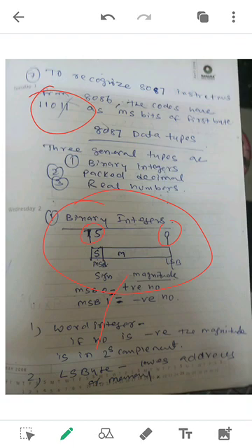The MSB, this one, the last bit, 15, is called the MSB. It has the sign. To represent the sign, you have the sign bit in the MSB, that is bit 15, and bit 0 is the LSB. So 0 to 14, you have the magnitude. Here you can see the M, which represents the magnitude, and the last bit belongs to the sign, which is used to represent whether the number is positive or negative. That is called a word integer.